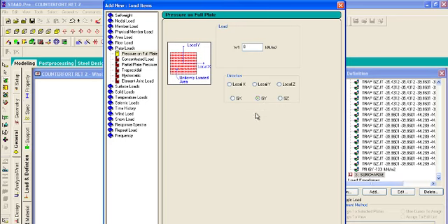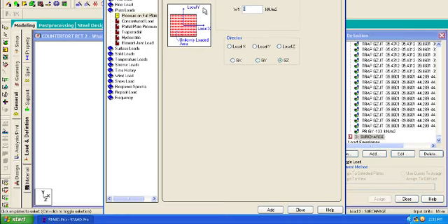This is going to be in the global Z direction, and then we have a surcharge action of 3.33 on the walls. Say add, and then we have in the global Y direction a surcharge action of -10.